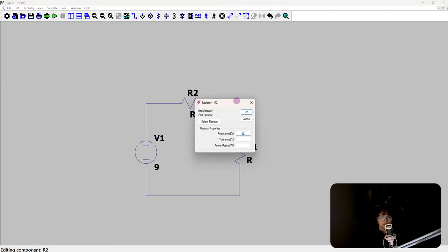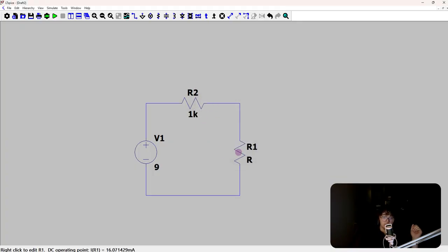For our resistors, let's do just 2 simple resistors. Let's do 2 1,000 ohm resistors in parallel. You could do 1,000. What if you get to 1 million? What if you get to 1 bajillion, right? You can actually type in prefixes automatically. Well, not prefixes, units. So 1, and then we hit K, right? And 1K will register to LTSpice as 1,000.